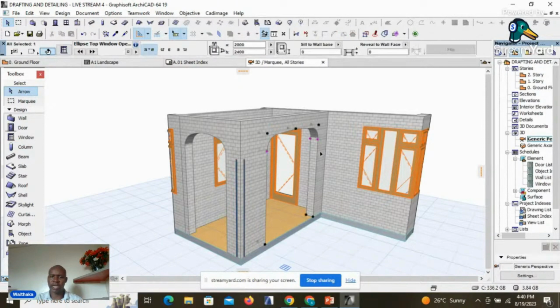We will start adjusting the arches. We can see this arch from our settings here. It has a range of 2,000 wide and a height of 2,400. So for us, we want to be left with an arch that has a resolution of 400, so that when it rests on this column, it will go up to 2,400 where our beams are starting, and that will define our arch.